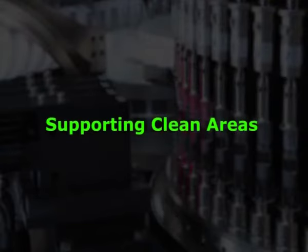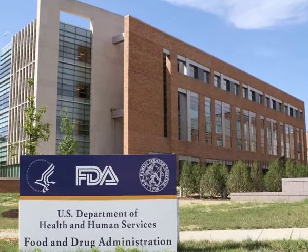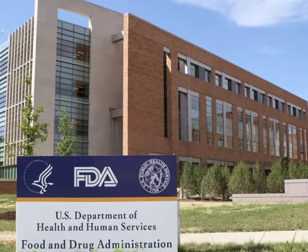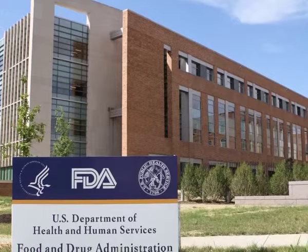Secondly is the supporting clean areas. The nature of the activities conducted in a supporting clean area determines its classification. FDA recommends that the area immediately adjacent to the aseptic processing line meets at a minimum class 10,000, which is ISO 7, standards under dynamic conditions.